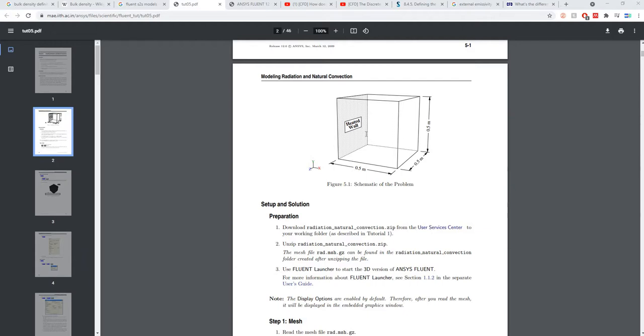Then we have to move on to the discrete ordinate radiation model, which considers the scattering of radiative energy by the medium. Okay, whether the medium is filled with air, gas, or some other liquid material, water, whatever it is. So this is what you need to know before we get into which radiation model to pick for a problem.